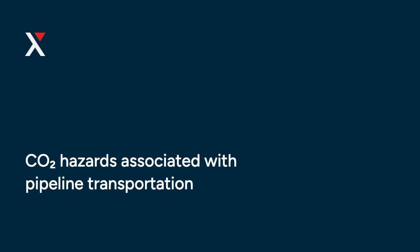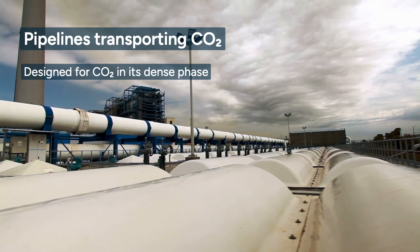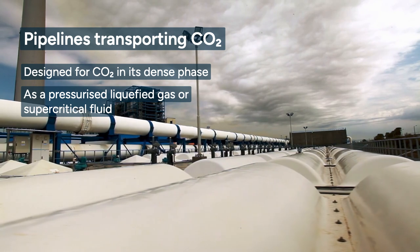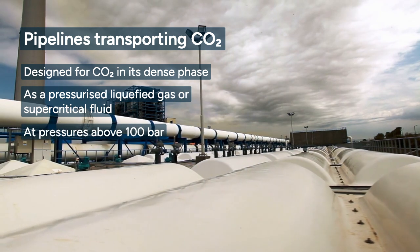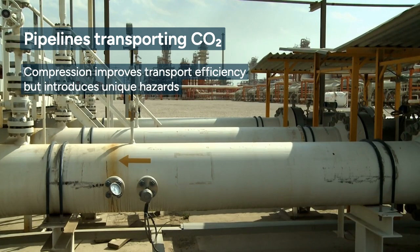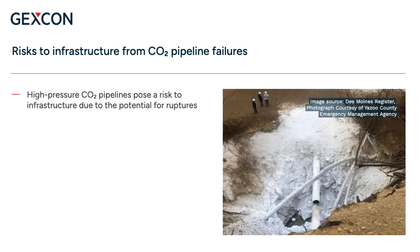Now let's focus on pipeline-specific hazards. Pipelines transporting CO2 are typically designed to handle this chemical in its dense phase, either as a pressurized liquefied gas or a supercritical fluid, at pressures exceeding 100 bar. While this compression improves transportation efficiency, it also introduces unique hazards. First, pipelines transporting highly pressurized CO2 pose a risk to infrastructure due to the potential for ruptures. That is because a rupture can cause a rapid release of pressurized CO2.